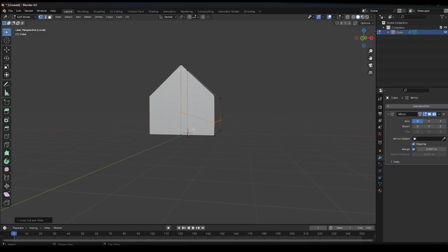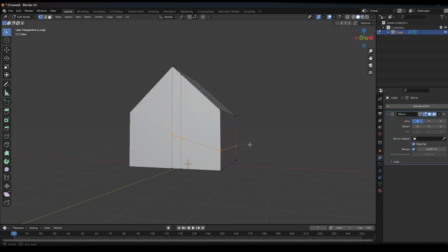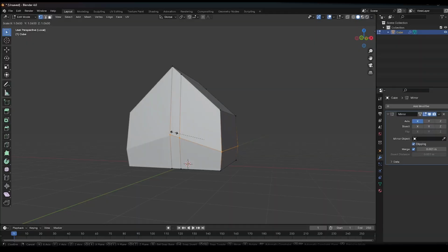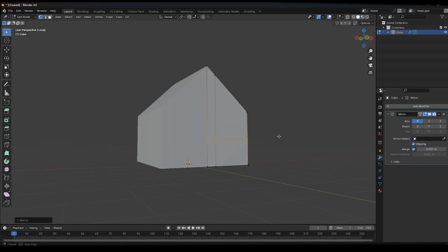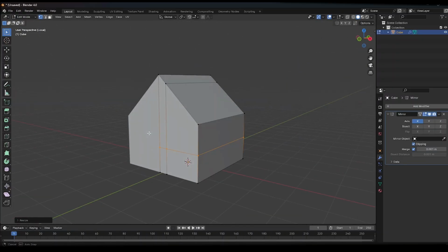I'm just going to press on this as it has been applied. From here, I'm going to scale this part up only, to make it flat. So I'm going to select this and press S. Now you can see that I can select it at each and every angle. You can also grab it or rotate it, but I want to scale it only on the Z axis. So I'm going to press on this over here, and you can also put in your number, 0, and there we go. We have fixed the slanted one into a flat one.